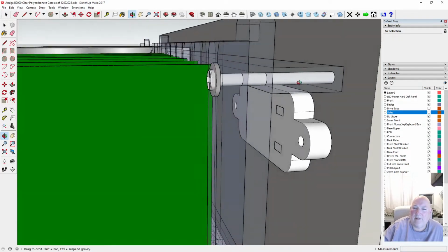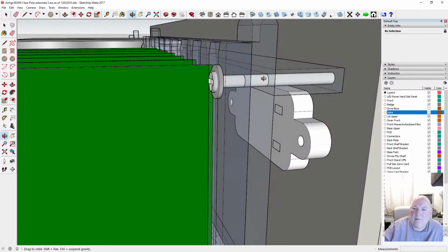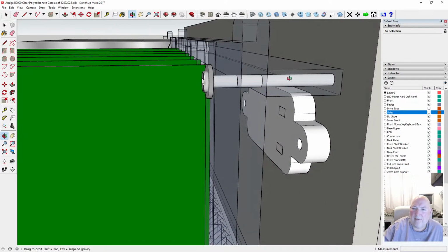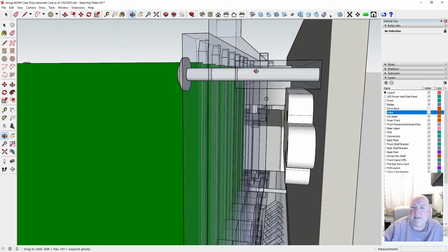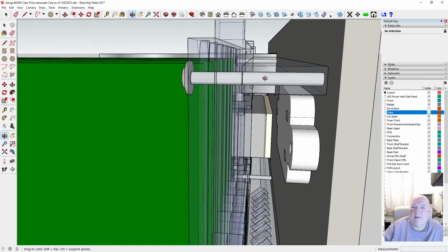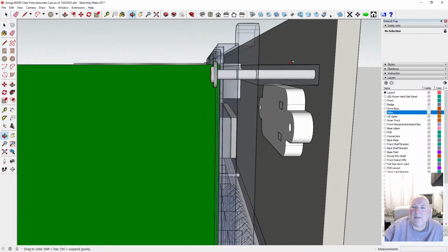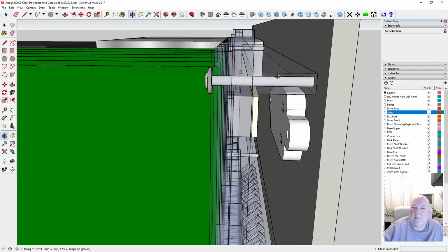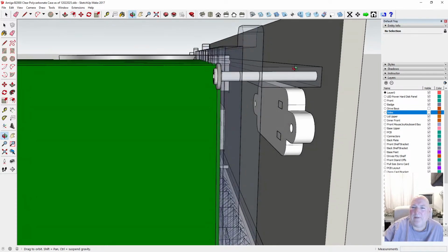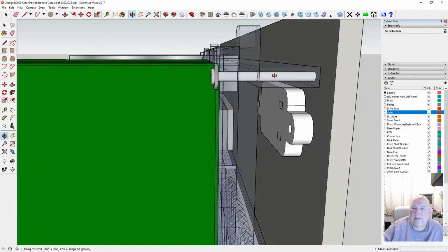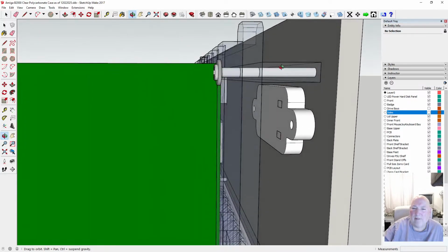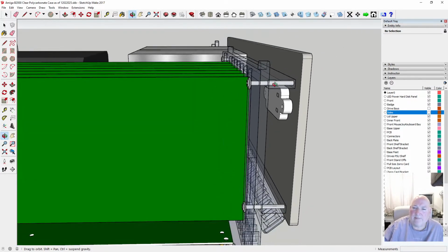Yes, you can try to mark them and cross point. You try and drill straight through the center of a piece of plastic. You might be able to do it on a pillar drill, but you'd have to hold this still in the vise. Your plastics would get marked. You have to put it in paper towels and all sorts of stuff. Drill it, and by drilling it, it would shatter it. Some of it's brittle.